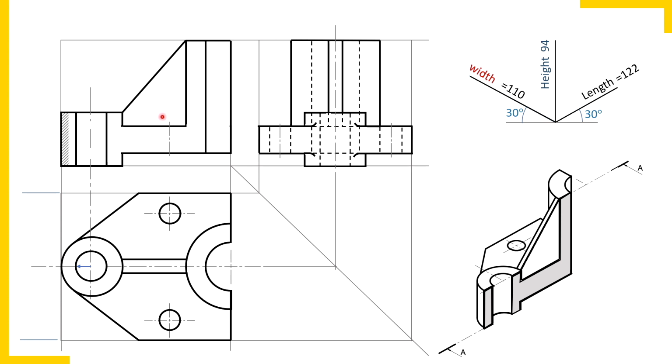So let's show the hatching lines. Watch here. 45 degrees inclined line, faint lines. So simply the newly generated surface we have shown by hatching lines, and original surfaces we have not shown by hatching lines. So inner surface of the hole, inner surface of semi-cylindrical slot. And why not hatching lines on the trapezoidal plate? Because that is a rule in sectional views, that largest surface of the plate must not have hatching lines on it. So this is how we have completed the three views: sectional front view, top view and side view.